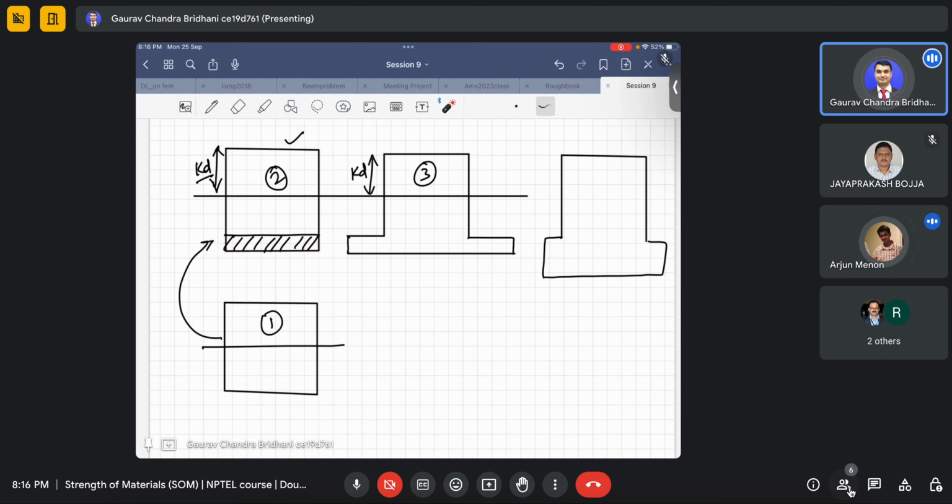In that case, it is a concrete example. So you have some reinforcement bars here. You say there is no tension in concrete, meaning concrete does not take tension, only compression. So you find the force due to the bars and equate it to find kd.